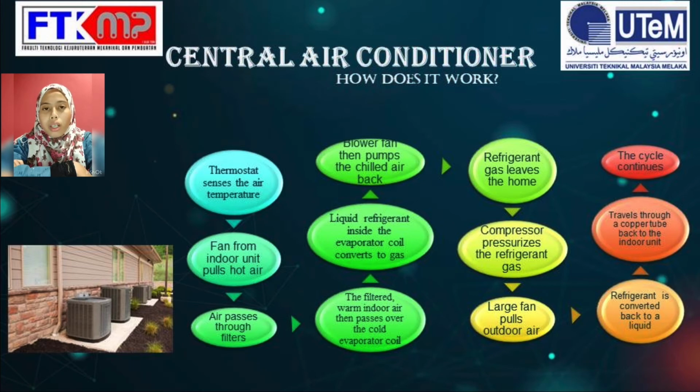During this process, the refrigerant is converted back to a liquid. It travels through a copper tube back to the indoor unit, where it passes through an expansion device, which regulates the flow of refrigerant into the evaporator coil. The cool refrigerant then absorbs more heat from the indoor air and the cycle continues.